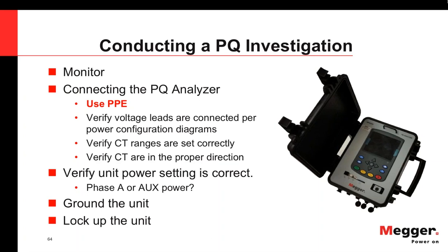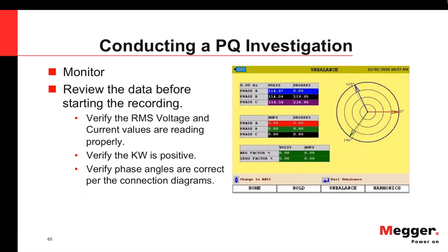Okay. Monitoring. You need to connect the PQ analyzer. Number one, make sure you have the proper protection equipment on. Always take safety first. Verify the voltage leads are connected per the power configuration diagrams. Verify the CT ranges are set correctly. If you're using flexible CTs, they can have multiple ranges on them.